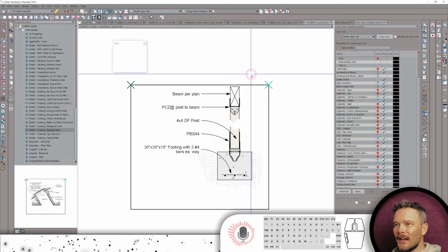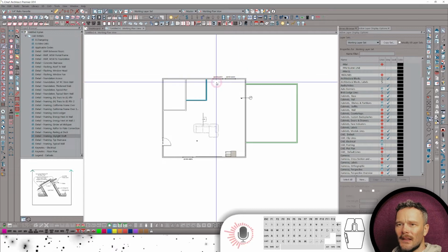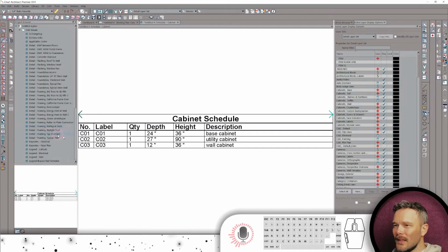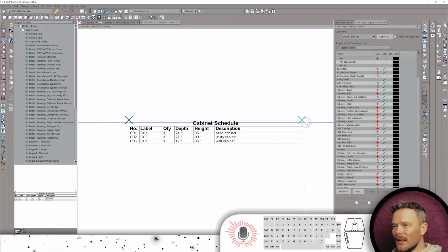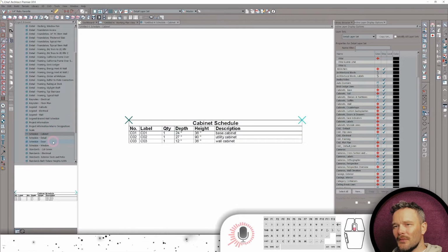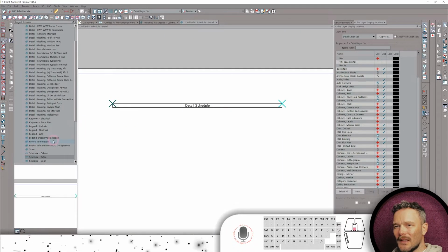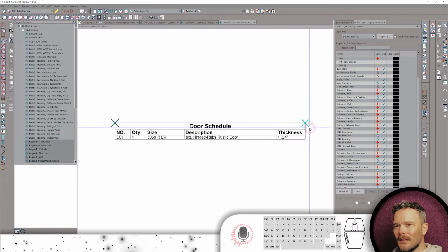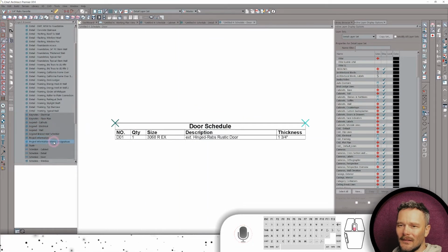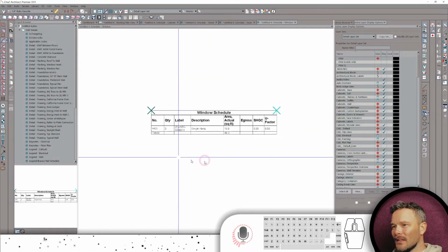I'm going to go ahead and close this out and several of our details out. And then I want to get into, well, we've got schedules. Schedules live inside of our CAD details. You're going to see here, I have 2 points placed on either side of the schedule. That's to keep all schedules uniform in size, so that if for some reason one of these schedules gets oversized, you can always snap it back to that point. And this is so that it looks uniform on the page when you send it to layout. So this is a specific workflow of mine. I really like everything to be uniform in looks.